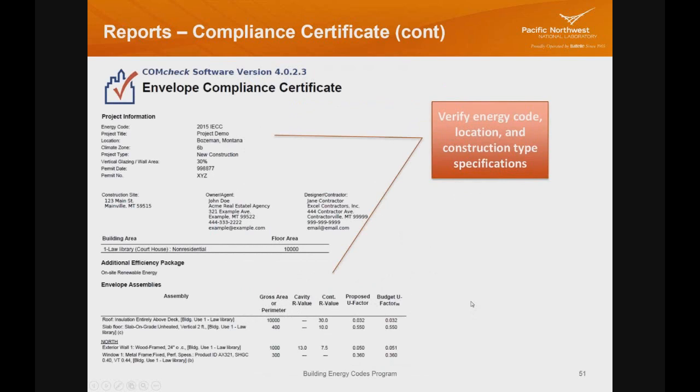So on the compliance report itself, and I've enlarged it so you can see each of these pages a little bit bigger, when you're looking at it, if I'm a code official or even the designer, first verify that you've chosen the proper code. This is big. There's a lot of code options in COMcheck.